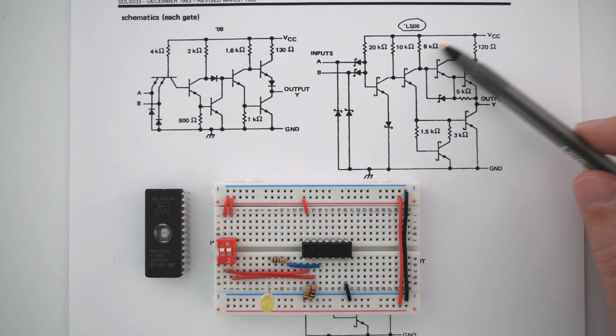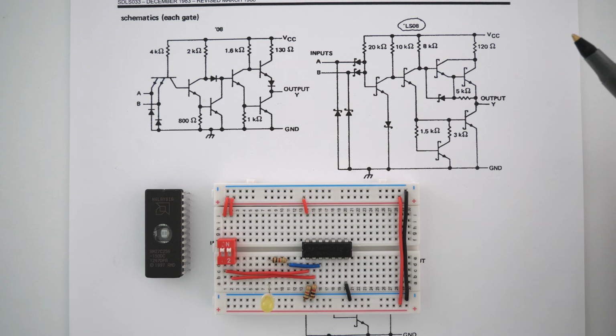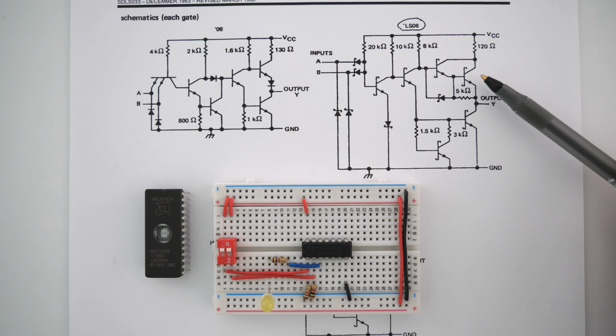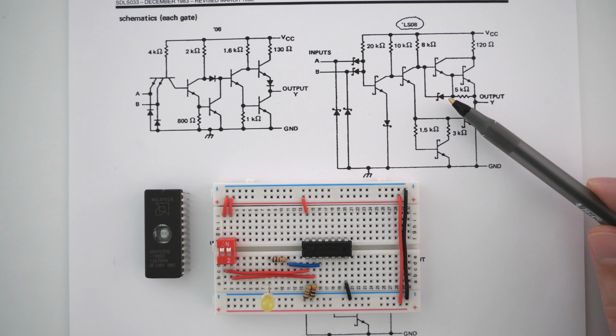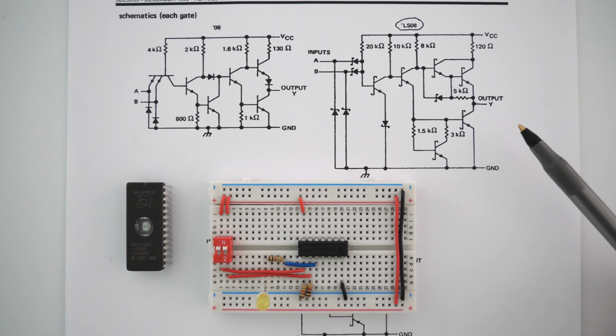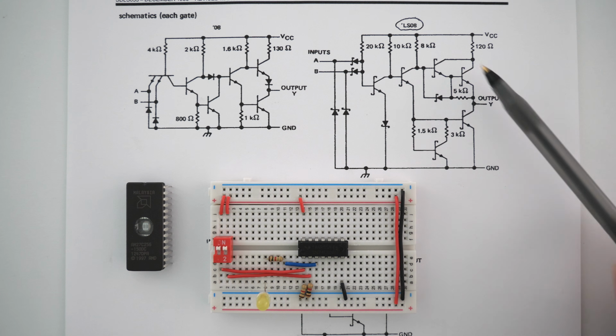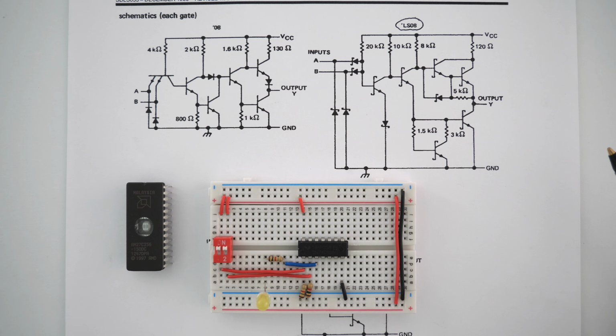This is the one that's built on the chip because it's the LS08, and this one is built with Schottky transistors and Schottky diodes. So this one is built for low power consumption, fast switching times, and has an overall robustness of the circuit, so it will work in a lot of cases. However, with that robustness might come some features that you don't like. So sometimes it's easier to build AND gate number 3, and sometimes it's easier to use these integrated